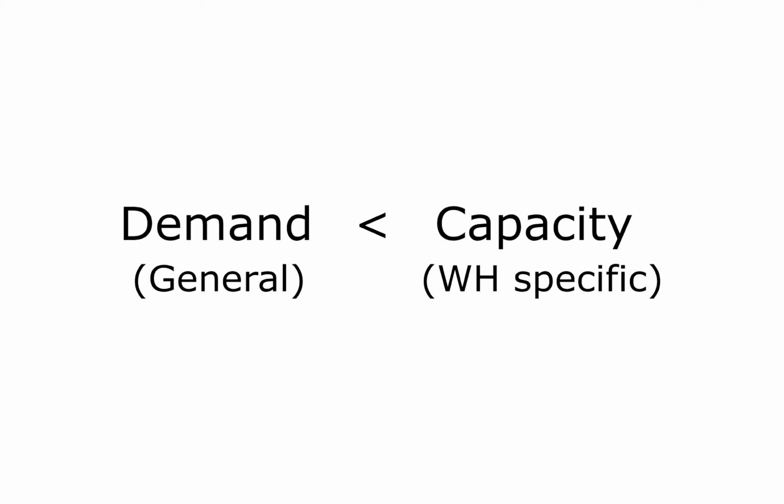Generally speaking, what we want to do as structural engineers is check that the demand, the loads bearing on our structures, are lower than the capacity of the structure itself. The term capacity means both strength and also stiffness, right?